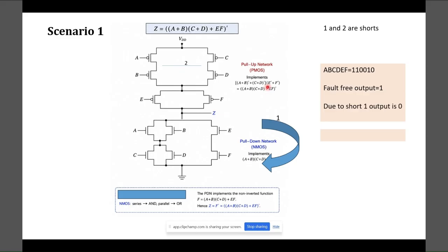C plus D, the whole complement can be written as C bar dot D bar. So C bar, because bubbles are here, C bar dot D bar. So E bar plus F bar, so parallel. Can you understand how this is happening? Based on De Morgan's law only, we go for the combination, parallel or series connection of MOS transistors. Okay, I think you got how a CMOS realization happens.